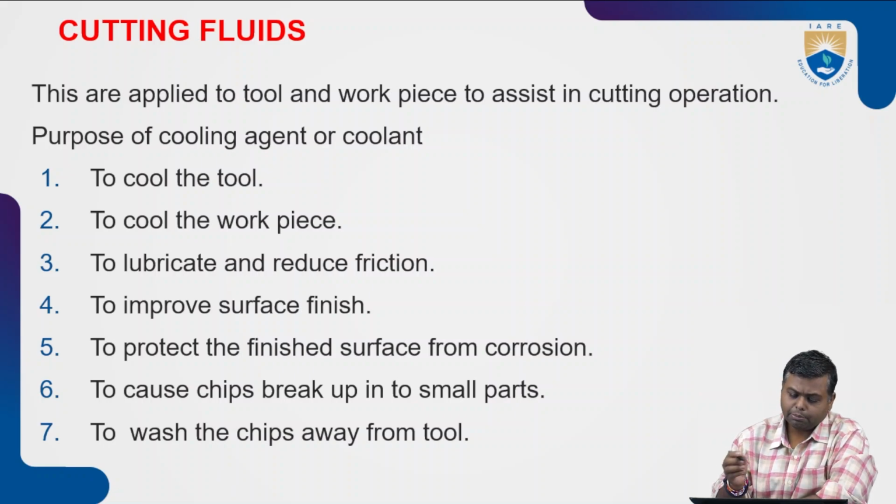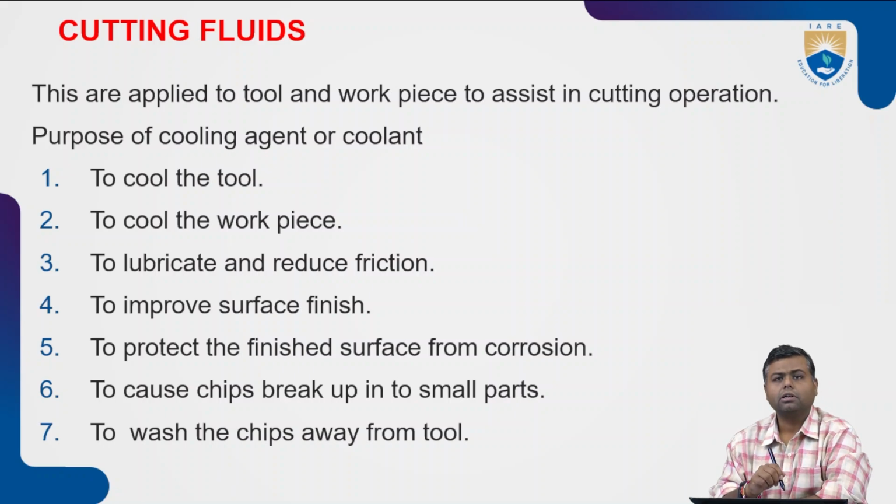Generally, they may be used for cooling the work or tool environment, to reduce friction, to improve the surface finish, to avoid corrosion on the parts produced, or for chip breaking or taking the chip away. But the general purpose of cutting fluids or coolants is to cool the environment, so that the heavy heat can be carried away by the coolant.